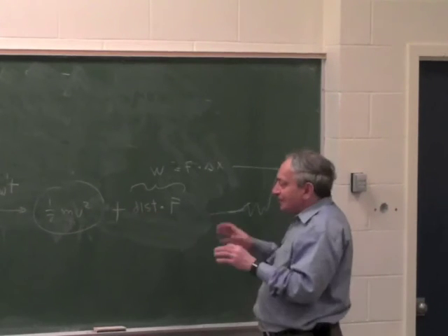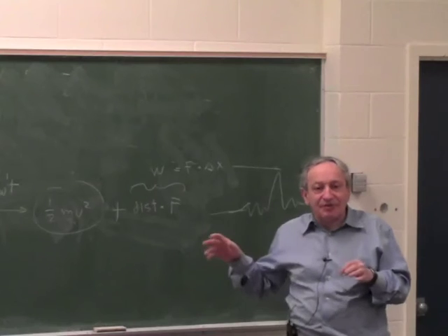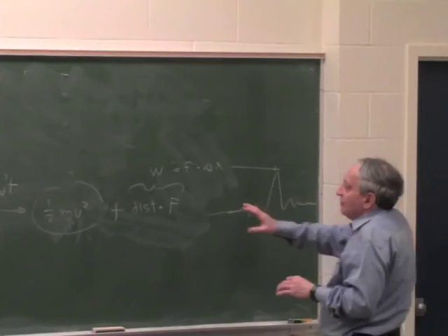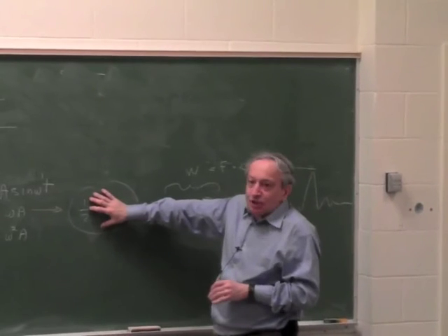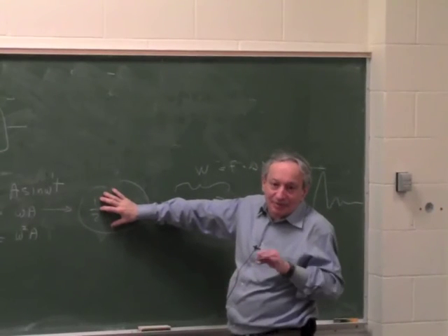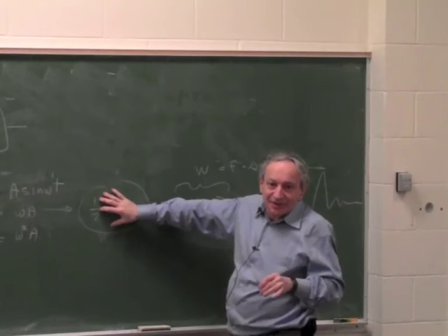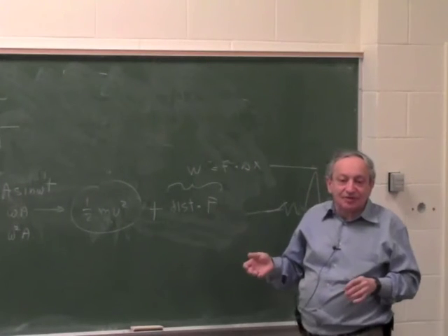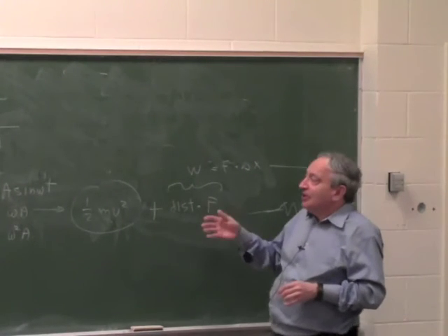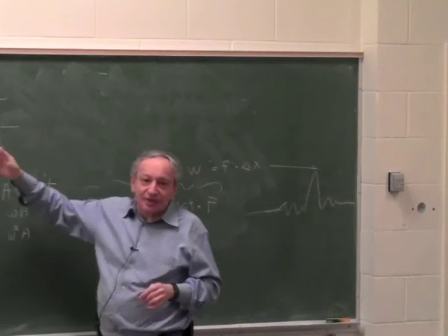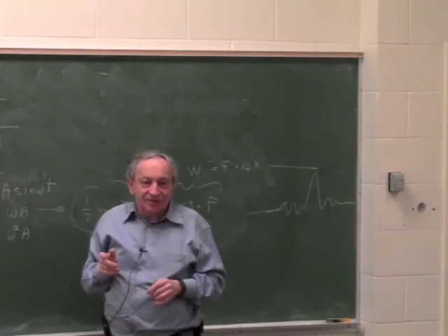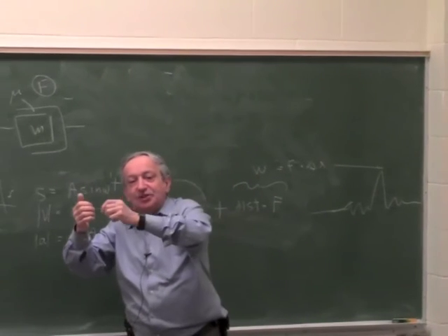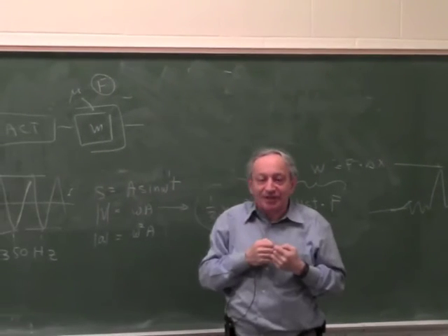So that's a very, very rough calculation. I'm not even getting into the exact calculation of the distance. I'm just saying in general you have energy here which is inertial, which theoretically is recoverable, but you never do it in small servos. And then you have work which is not recoverable, for example friction or opposing. If you have a constant force, theoretically that's recoverable. Because if you go against a constant force, you push it and you put in energy, and then the force pushes you back and you get the energy back.